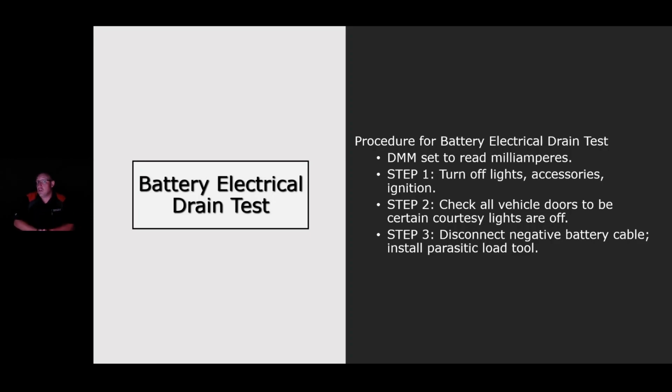So some modules on a car with a lot of modules on it, for example, like a Mercedes or a BMW that has 100 modules on the car, you might not get that car to completely shut down for 2 to 3 hours. So if you're trying to do a car like that in lab, you might not get that car to shut down the entire lab from parasitic drain and be able to formally check the parasitic draw on that. That's where the Power Probe hook comes in.